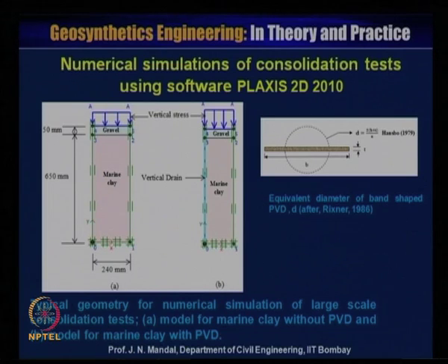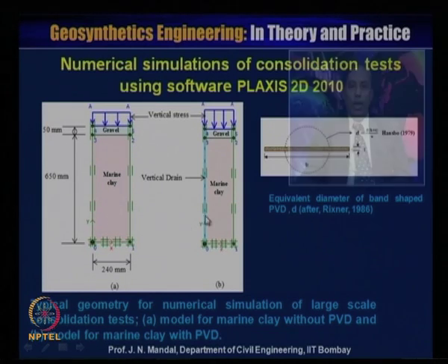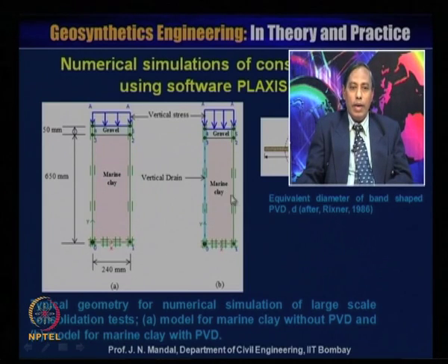So, some numerical simulation of the consolidation test using the software Plaxis 2D 2010 has been performed. So, here is the typical geometry for the numerical simulation of the large scale consolidation test. This is the model of the marine clay without the prefabricated vertical drain, and this is the model for marine clay with PVD.